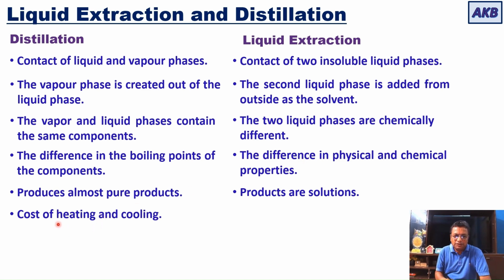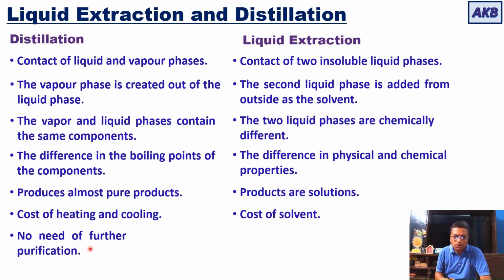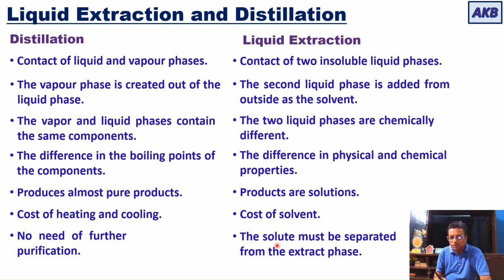Then in the case of distillation, cost of heating in the reboiler and cost of cooling water are involved. Whereas in the case of liquid extraction, cost of solvent is involved. In distillation, there is no need of further purification, whereas in liquid extraction, the solute must be separated from the extract phase, and for that we need to use another separation method, and most of the time the separation method that is used is distillation.